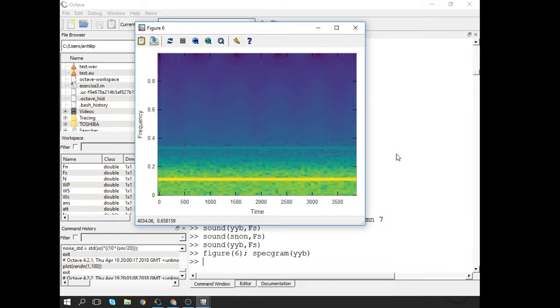But when you have, say, music and that kind of stuff, you can basically reduce anything that is less than 40 dB from the highest, because your ear is saturating and these elements are saturating already there. Your brain does not anymore distinguish between different components. That's why you can really compress music into very small packages, because you can get rid of a lot of components there.